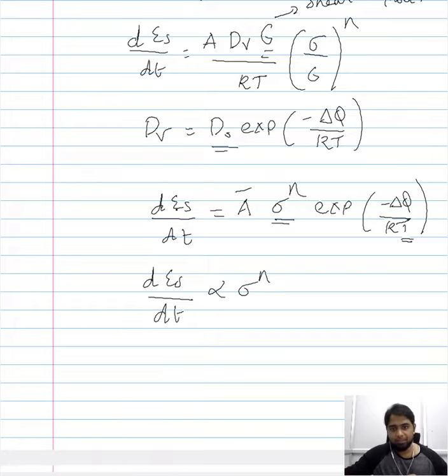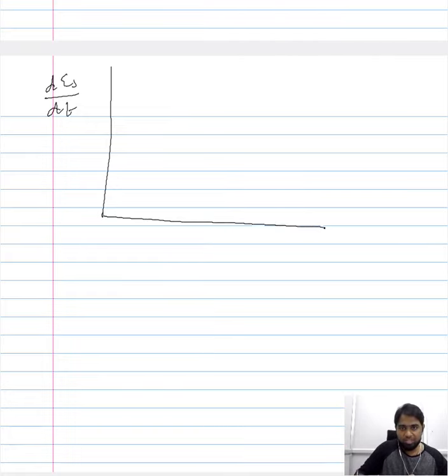So we ended the final segment of the previous lecture by plotting a curve that relates the creep rate, or the steady state creep rate, with the normalized stress. The normalized stress is the ratio of the stress and the shear modulus. We saw it comprises three regions: a first region, a second region, and a third region.